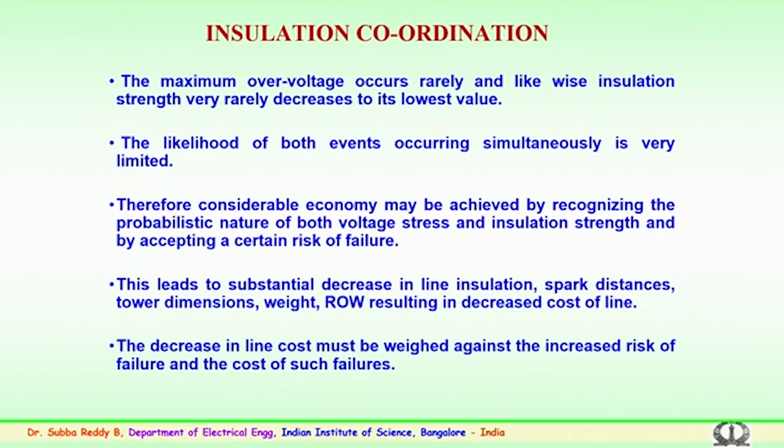This decrease in line cost must be seen again against the increased risk of failure and the cost of such failures. So, the design engineers have to bear in mind while designing proper insulation that it is not required to over design the insulator or under design the insulation. The cost must be weighed against the risk of failure and the cost of the failures which may happen in the system.